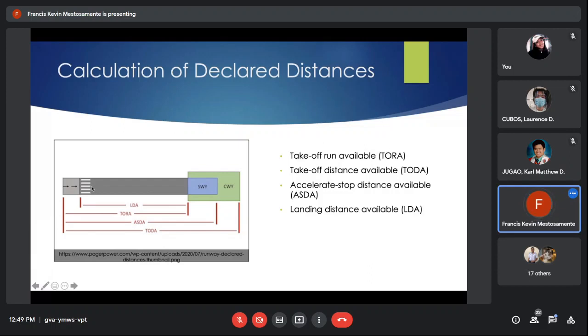As you can see, when taking off, we gain speed, and at half of the runway, that's around 100 knots, or around 60 to 80 for smaller aircraft. So we need a larger or an extra paved surface for the braking distance. And that is the primary purpose of the ASDA. And I mentioned earlier, also for the landing, the aborted landing.